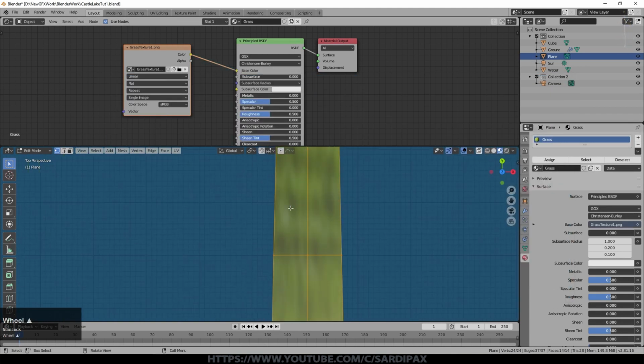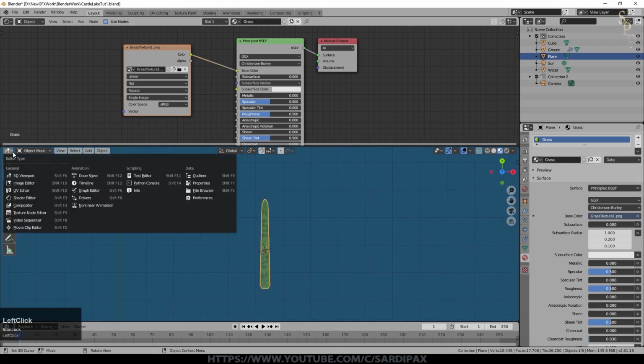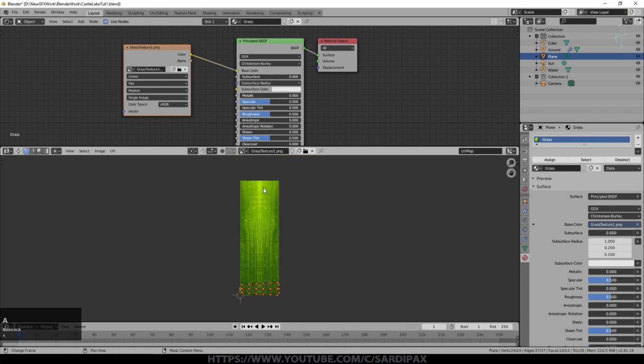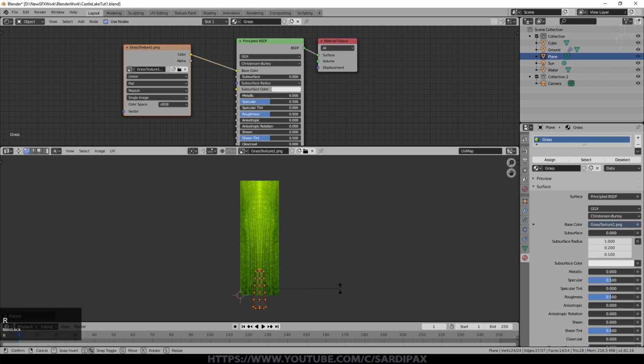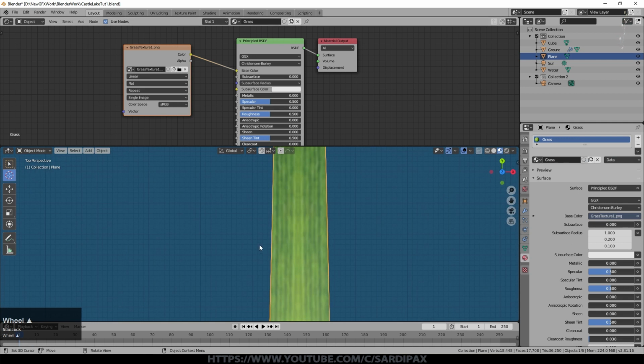So we're in preview mode, but you can see there it is. Looking slightly odd at the moment, and I know the reason for that. If I go to the UV image editor, go to edit mode, there is our image, but you can see our blade of grass is lying across our image. So we'll rotate 90, and in fact I'm going to rotate 180 at that point, because clearly that wider bit is the bottom of the grass blade, and I actually want that to be lighter than the top. You could just paint your own texture, of course. So now if we look at it, we've got these nice striations.